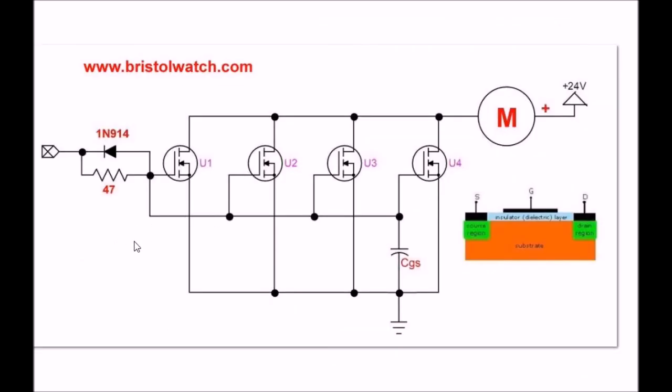Here is another variation of connecting the MOSFETs in parallel. You can put this resistor in the gate circuit. This would slow down the discharge surge. You might even reduce it to a lower value, such as 10 ohms, 22 ohms, whatever you want. You can do that to connect it to a gate or whatever. The 1N914 serves the purpose again as current rushes through the 47 ohm. The generated voltage spike is taken care of by the 1N914.